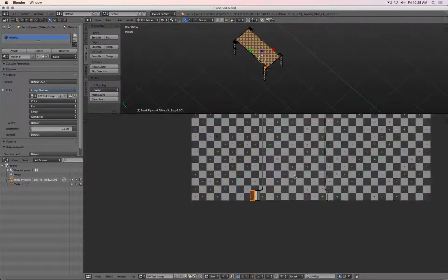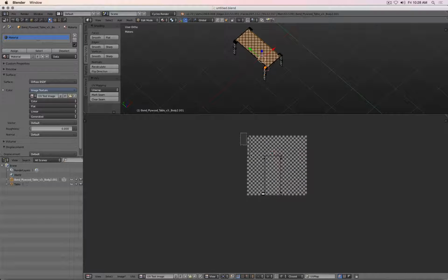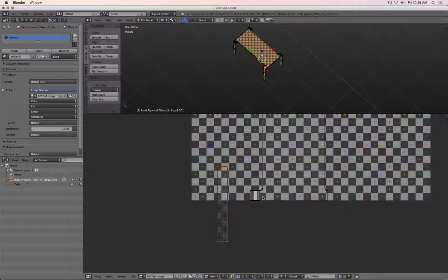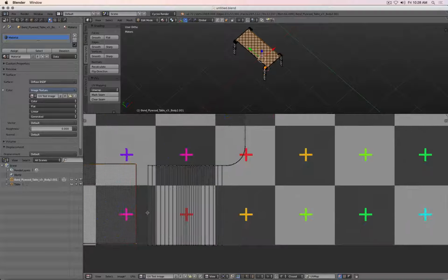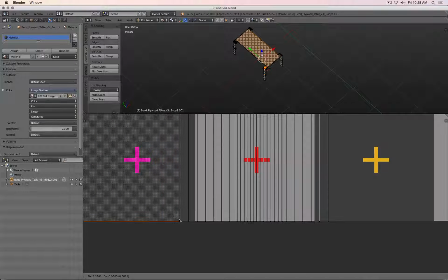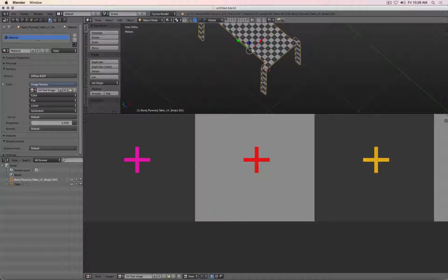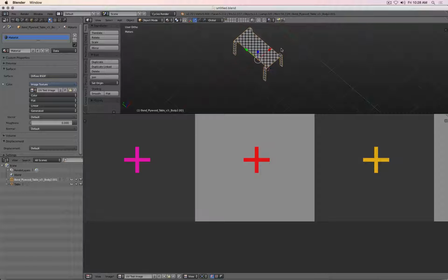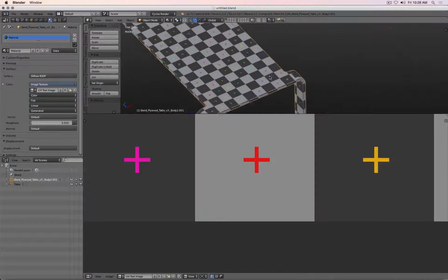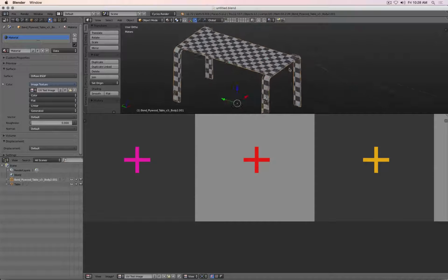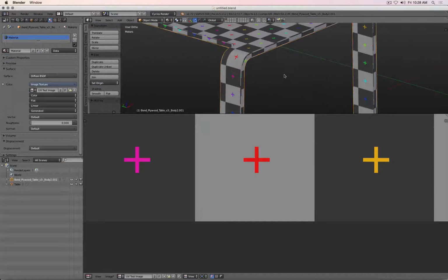Click on this bigger rectangle. And I currently match them minus 90. Maybe should work. I match them in a way so that my UVs perfectly sit on each other. And for example, I would do this amount of work mainly only on the surfaces I see. You don't really have to do everything from below. What you don't see and what you're not going to render, do not spend any time on it. Otherwise, it would be a waste of time.